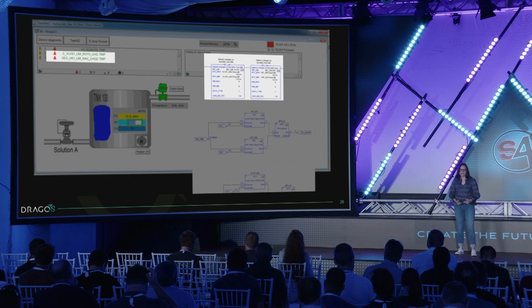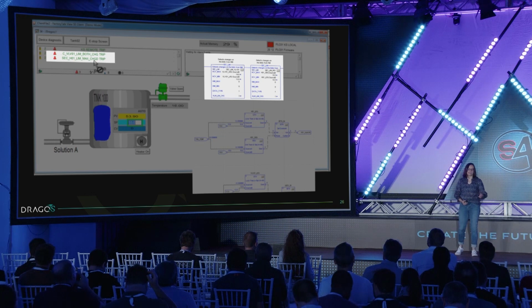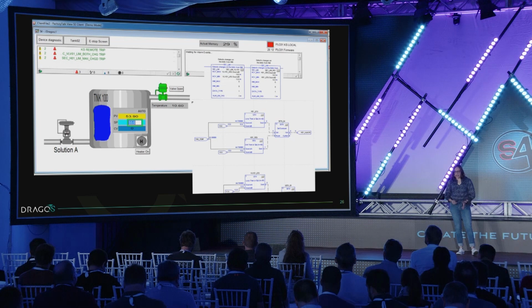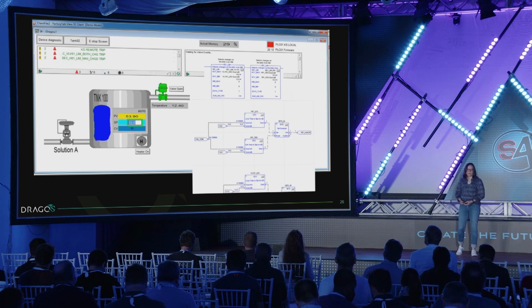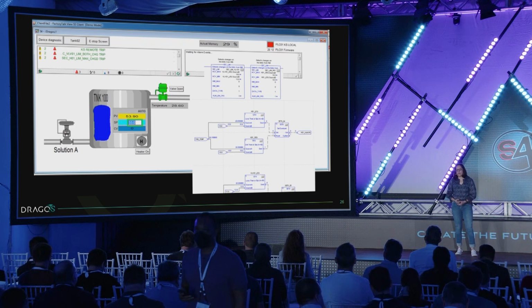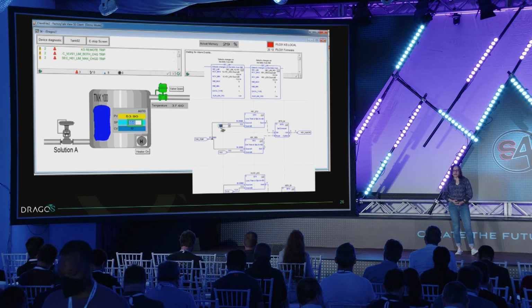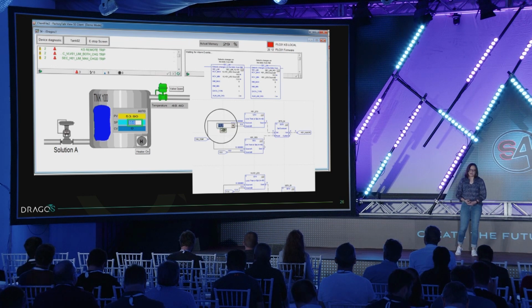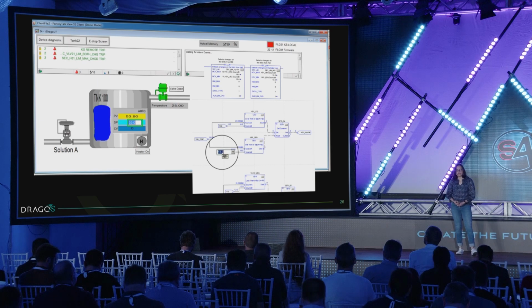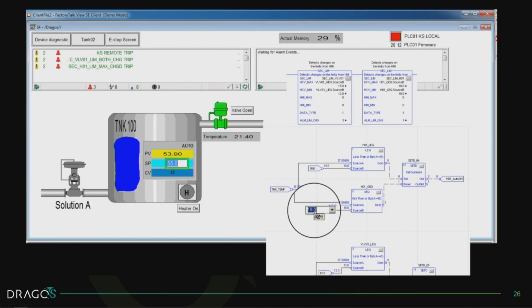And another thing is that, for example, in the valve, I changed both limits. So you don't want to show them that maximal and minimal. So you just create one alarm that it says both limits have been changed. So the less alarm, it's better to have it for the operators. And the things that they can also be relevant. And I'm just showing how the blocks are working and the limitations that you have. Now I'm just going back to the values because you cannot get rid of that without getting back to what you have hard-coded.